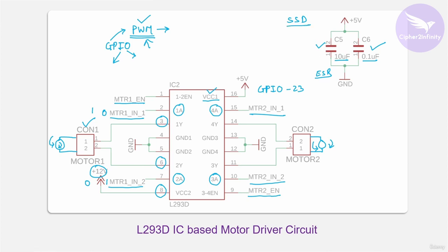if your power supply is a little noisy, then based on the noise or the ripples which are there on your power supply, you have to select the appropriate value of capacitor. We discussed the impedance versus frequency plot for the capacitor, and we saw that based on the frequency, the capacitor is going to provide different impedance, right? So based on the ripple frequency, you have to select the appropriate value of capacitor here, and that capacitor value will change from circuitry to circuitry, or hardware to hardware.